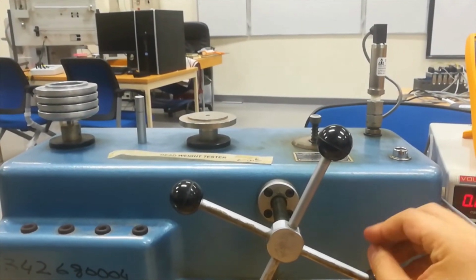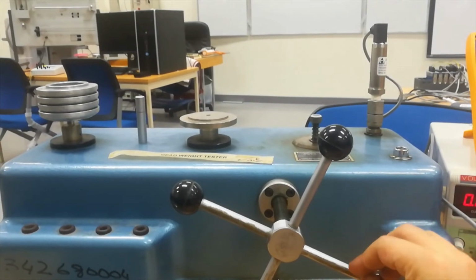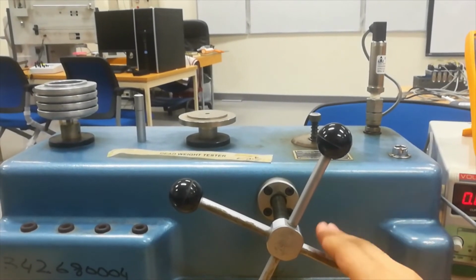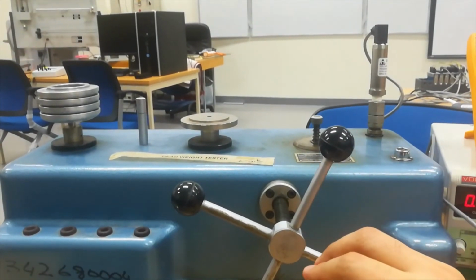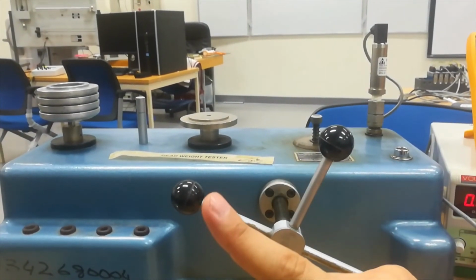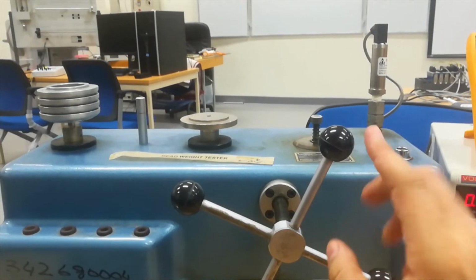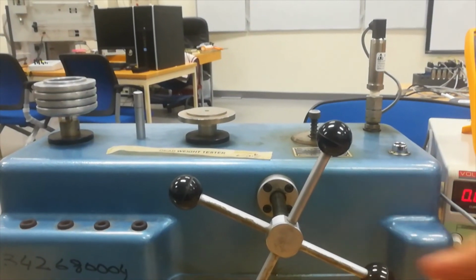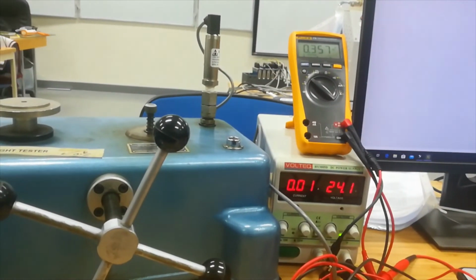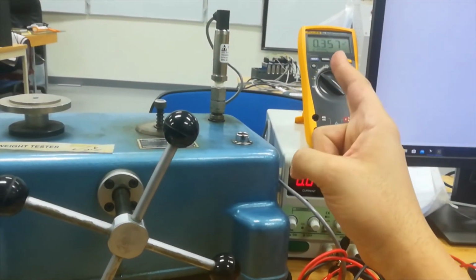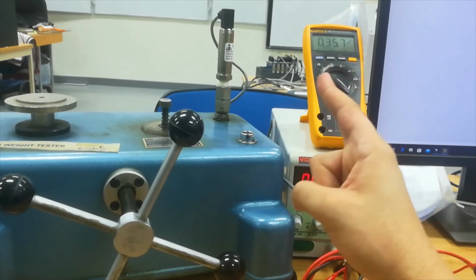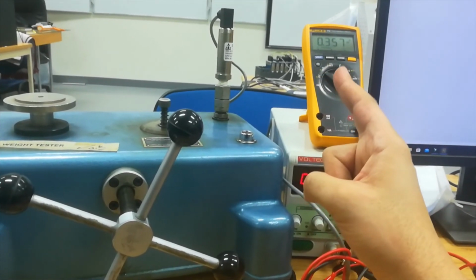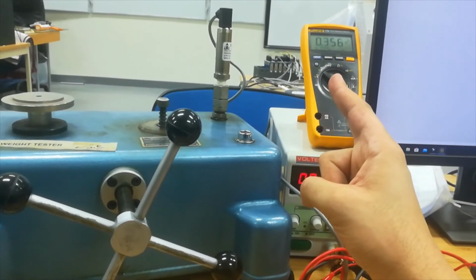Okay? So what is the benefit, or what is the target from using this screw and this valve? In order to trap the oil inside and make sure that the pressure from these weights is reflected to the pressure transducer. Okay? And now I need to go to the voltmeter and read the value, which will be 0.357 or 0.358 volt. And I want to read the same value from the data acquisition card.